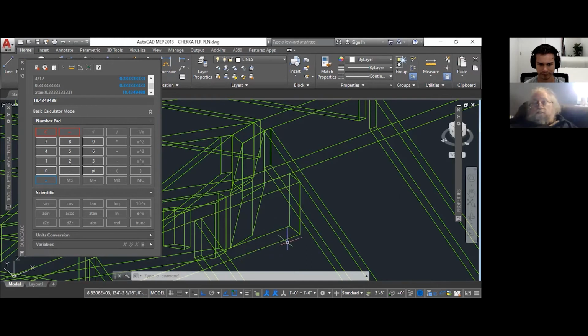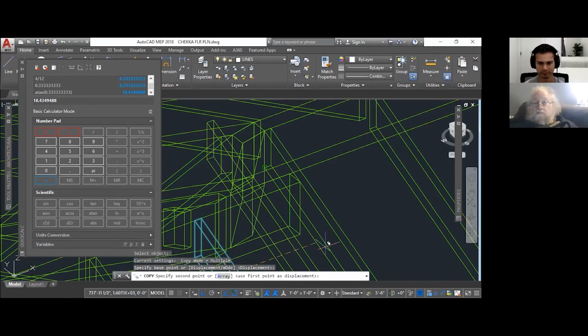You see how I've run this ridge all the way over to hit this common? I do that because it makes it easy to set it up. All I have to do is take one of these commons over here and slide it over there next to that common and scribe it to mark it. And that's where that ridge runs in. That makes it easy to set it up so that it planes correctly.